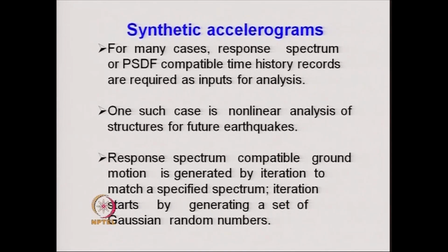Next we come to the synthetic accelerograms. For many cases one may have to obtain a response spectrum or power spectral density function which are compatible with the time history records, or for a given response spectrum or a given power spectral density function one may have to calculate synthetically a compatible time history record.